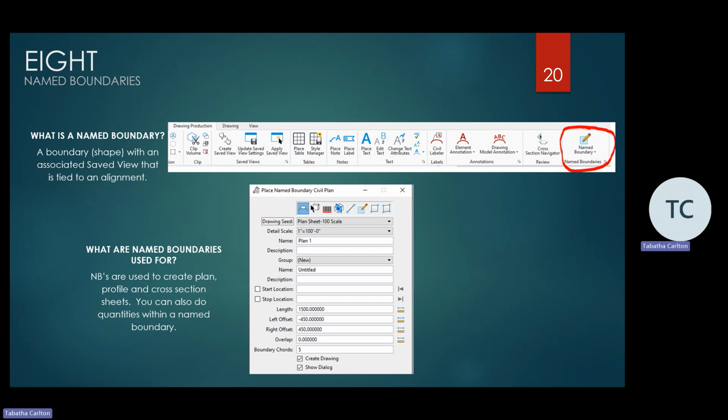Is the GDOT workspace copy pulled off ProjectWise or is it on your hard drive? I'm pretty sure the workspace is set up in ProjectWise, but I'm not sure exactly how it works. When you open the file and it downloads to your C drive, that file is fully on your C drive, like the seed file and the workspace and all that. It seems to work fine.